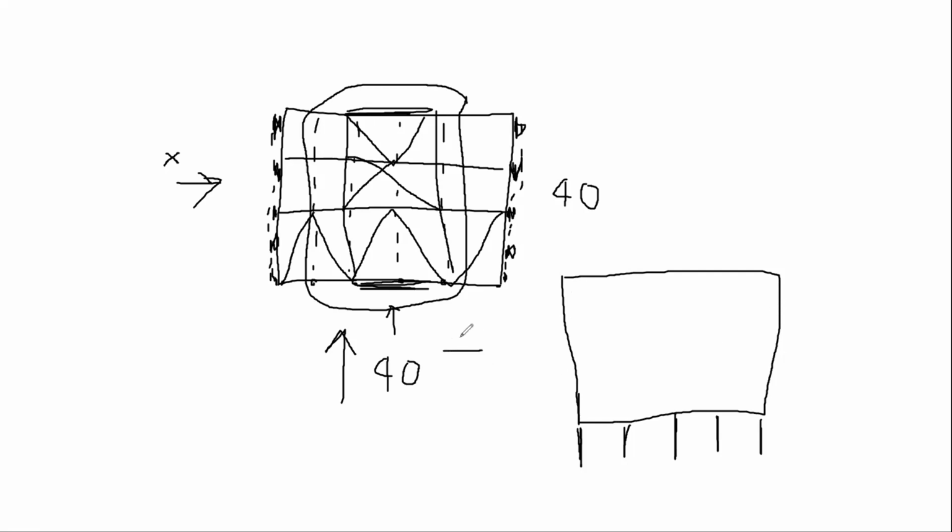And in the Y direction, if you wanted to, you could withstand your earthquake forces with shear walls or moment frames like that. So there's so many options that you as an architect have. And once again, you make the choice based on your program and your design concept.